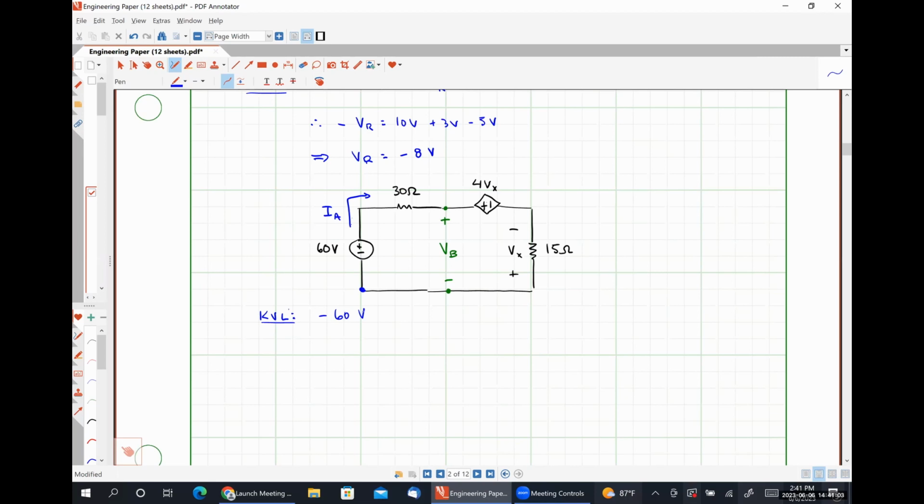So we have to assume one. It is impossible to make the wrong assumption here, as long as we wind up applying Ohm's law correctly in a couple of moments. So do you guys want the positive polarity terminal of the voltage drop across the 30 ohm resistor to be on the left or on the right?